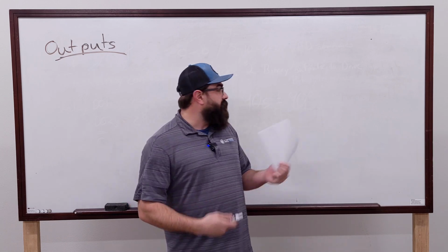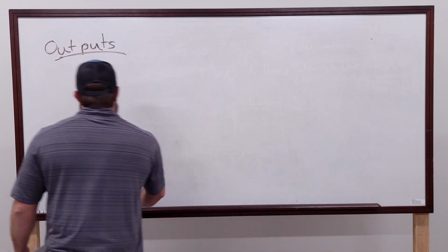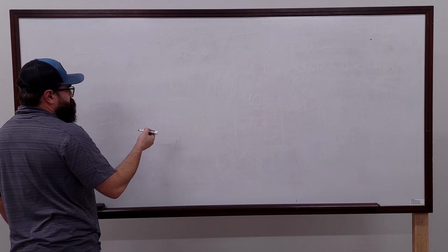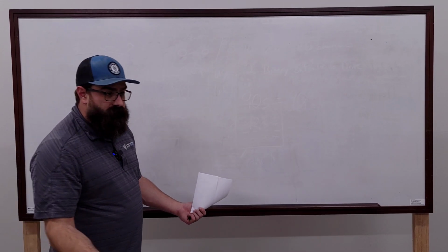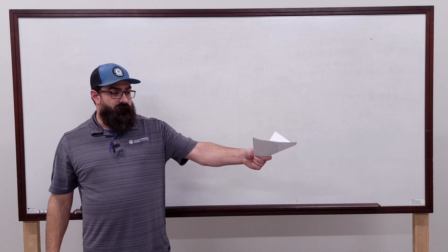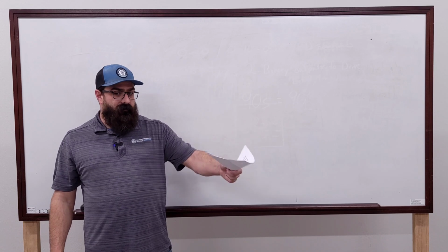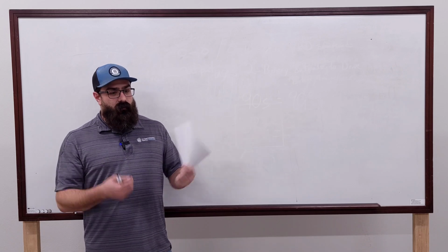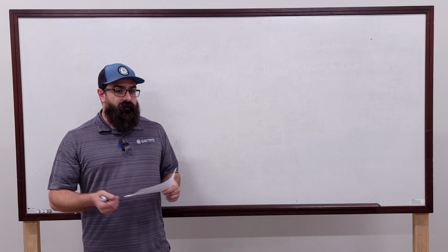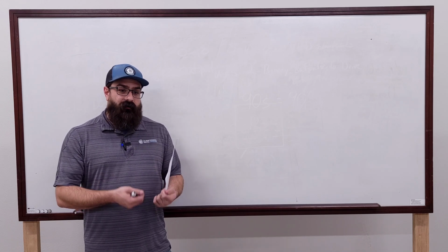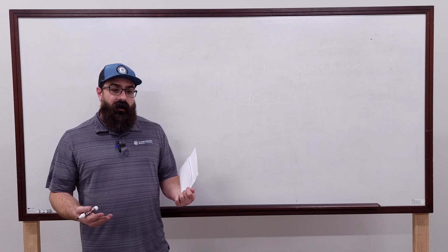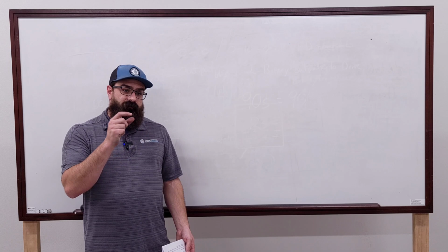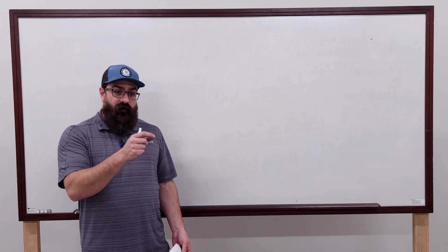So let's say I have an end switch on a damper, okay? And I go look at that damper, I know it's 100% open. I can put a meter on that end switch, make sure the contact's closed. I can go back to the controller, unwire the wire for that input from the controller, then check that wire, make sure that wire has the contact as closed, so we know we don't have a cut wire. The next thing to do would be to jumper off that input, right, with something that works.